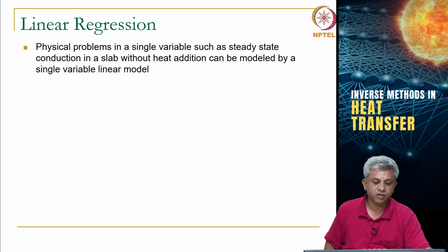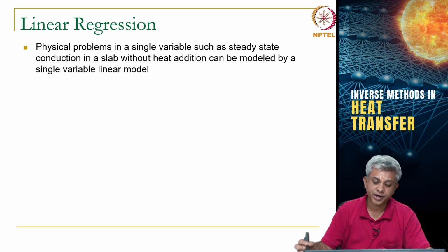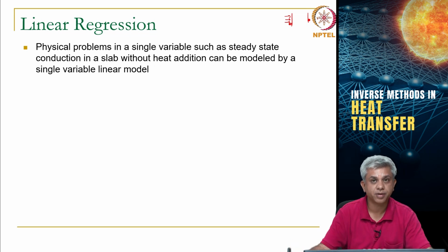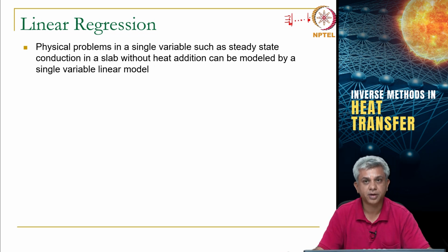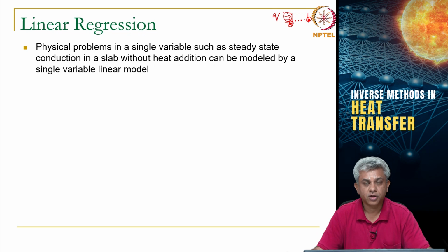So, when you have physical problems such as what we did again and again this week, which was steady state conduction in a slab without heat addition. We took a slab, there was some heat transfer because of the gradient in temperature in the middle, and we kept some thermocouples in the middle and made measurements and tried to see if we could figure out the end temperatures as well as the heat flux within the slab using just inverse techniques.